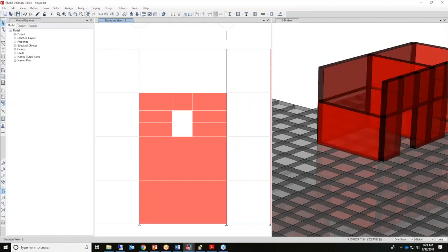Or there's something called the draw wall openings tool, which gives me the ability to drop in an opening in any location. You know, I'm just going to arbitrarily generate one here. So I dropped in an opening in the specific wall. But the question is, okay, you put an opening in the wall, what about meshing? The answer is yes, I need to mesh this wall as well. You can't just put an opening in the wall and not have it meshed for proper load distribution.